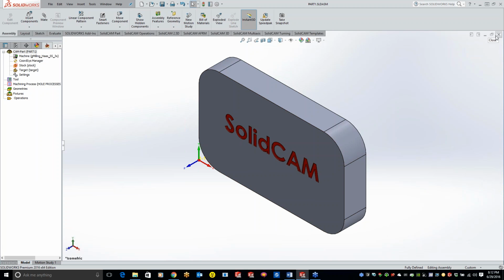Now, if I hit the red X over here, what we're doing is we're actually closing SolidWorks and SolidCAM at the exact same time. So if we have a larger CAM file, what will happen is SolidCAM is trying to compress all that stuff into that zip file, and SolidWorks is trying to shut down at the same time, and sometimes it will pop up saying it didn't get closed in time, and it will kind of pull out of your temporary folder.